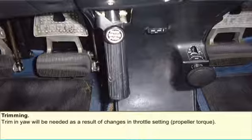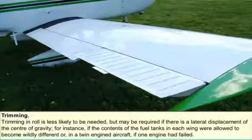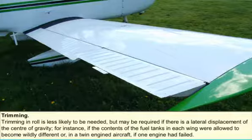Trimming in yaw will be needed as a result of changes in propeller torque, or if there is asymmetric power on a twin-engined aircraft. Trimming in roll is less likely to be needed, but would be required if there was a lateral displacement of the centre of gravity. For example, if the contents of the fuel tanks in each wing were allowed to become wildly different, or, in the case of a twin-engined aircraft, if one engine had failed.